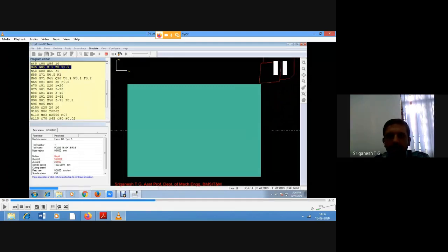Then I'll go for next command G01 X56 Z0. So I bring the tool back inside over here. Okay, and I'm ready for the facing operation where I want to remove another 1 mm of material. So I've moved the tool 1 mm inside. Yeah, and now it is going to read N45 G01 X minus 1 Z0.